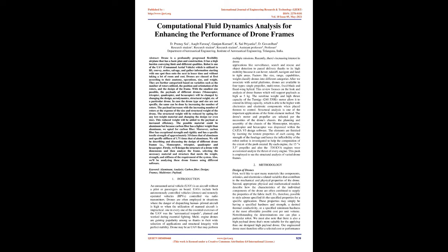The possible material could be aluminum, but because carbon fiber has a lighter weight than aluminum, we opted for carbon fiber. Moreover, carbon fiber has exceptional strength and rigidity and has a specific tensile strength of approximately 3.8 times that of aluminum and specific stiffness of 1.71 times that of aluminum.